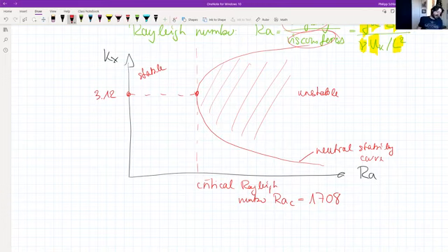And now what we would like to do is use our little MATLAB code that we're going to develop, to see whether we can actually match this point, whether we can see that if we are a little bit below in terms of Rayleigh number, nothing happens. I mean, the flow is what we would call stable. And if it's a little bit above, we would then see that the flow would exponentially grow and reach an equilibrium, a nonlinear saturated state with non-zero motion.